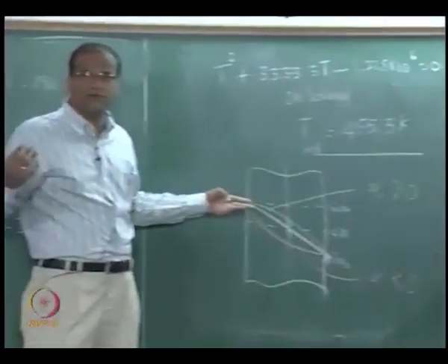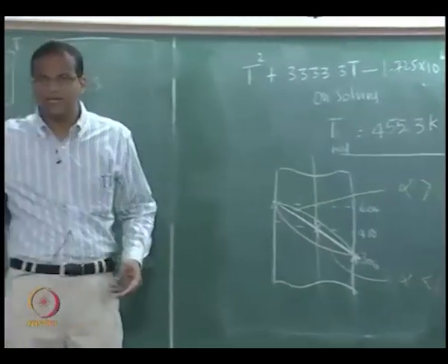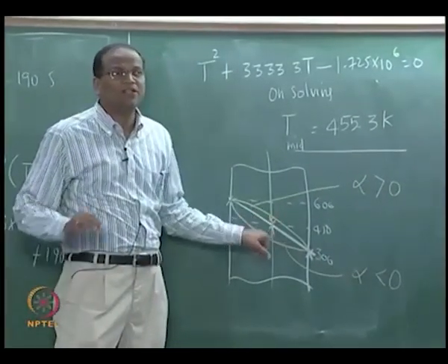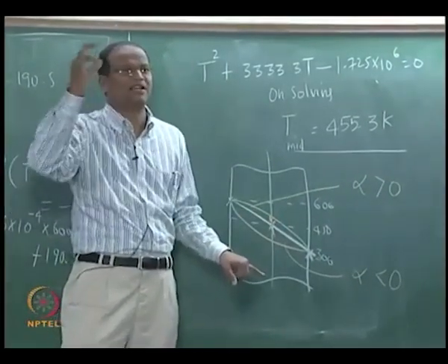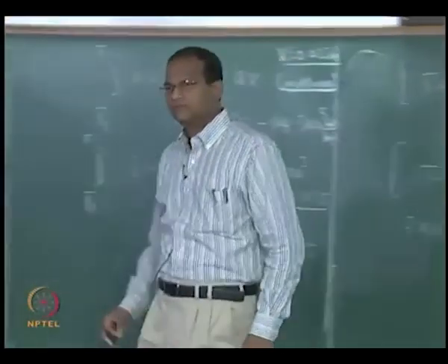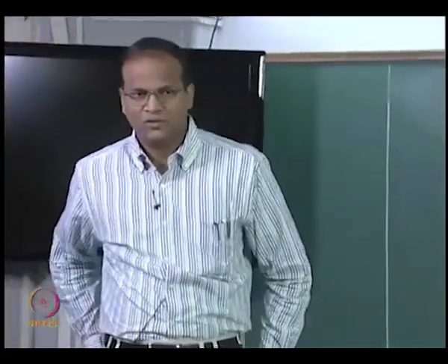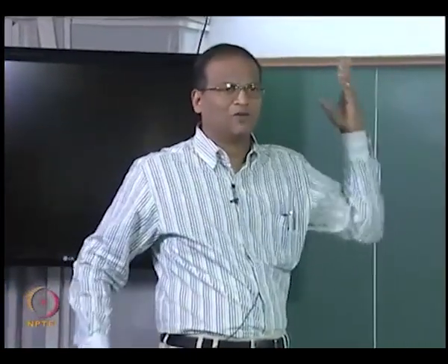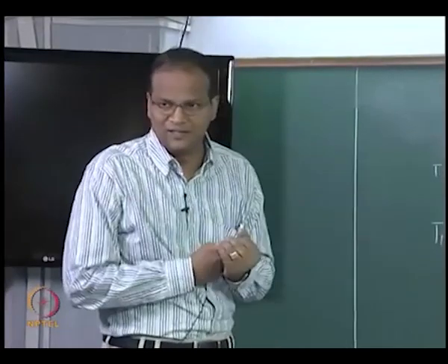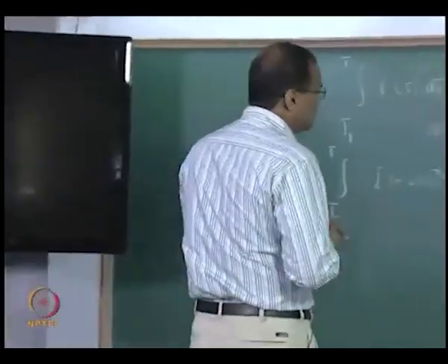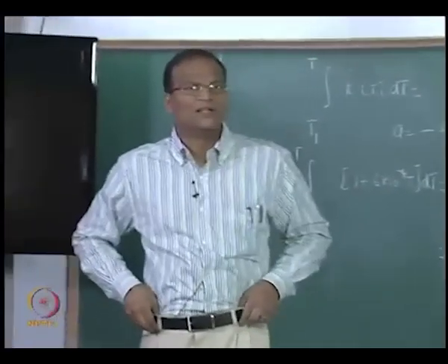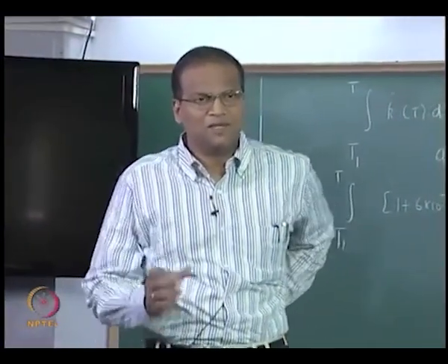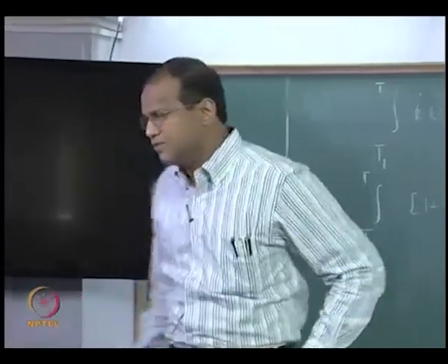Suppose I had told you like this, you may or may not believe me, that is why I took a detailed approach where we numerically solved and I proved that for alpha greater than 0 the mid plane temperature will always be higher than what is predicted by the arithmetic mean temperature difference, okay, right. So once linear we can have a quadratic fit for thermal conductivity and all this. So now you know the way of handling this, right, and oftentimes for large variations in temperature this constant thermal conductivity model is no good. If the temperature difference is small, it is alright to use this, okay.